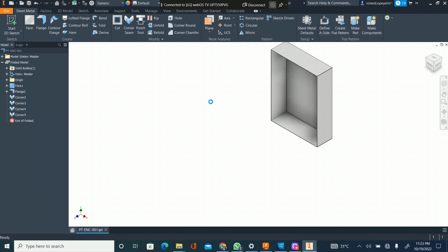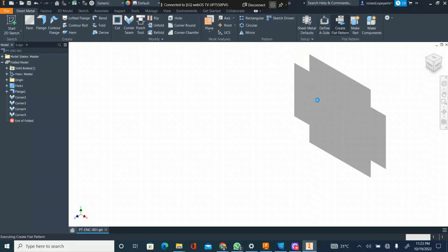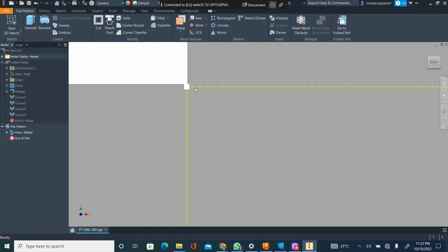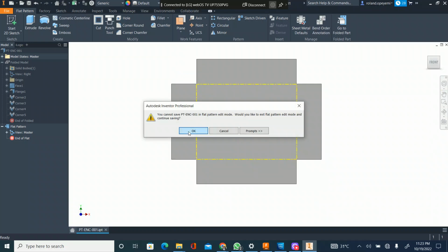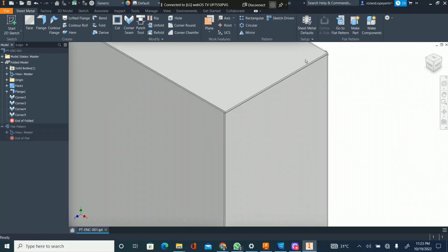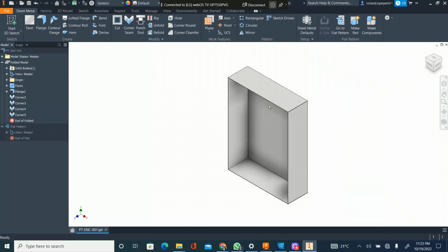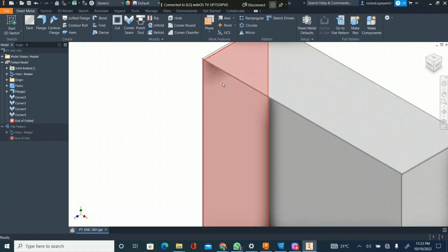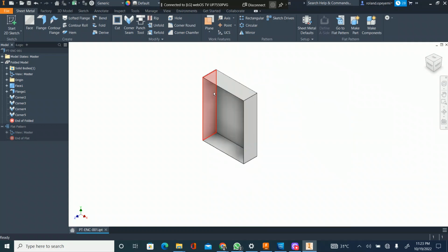Then you do save. We now create a flat pattern. You know, unfold everything, and you have your bend lines. So that's how it's going to work. What we try to confirm is this depth. Hope it won't be too much for bending, such that when you're bending this side, it won't clash with this side if you bend this first. So the press brake personnel asks you in achieving the stacks. Well, during your design, you want to ensure that you don't give them complicated concepts that will make things difficult. So those are the things we look at.